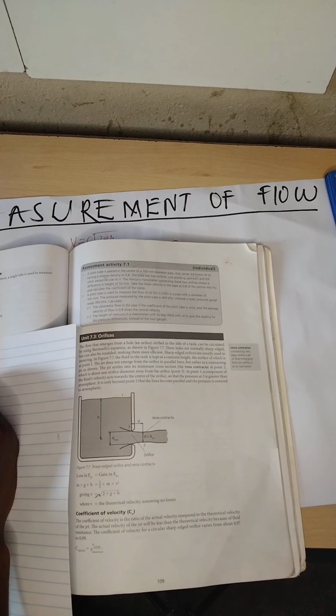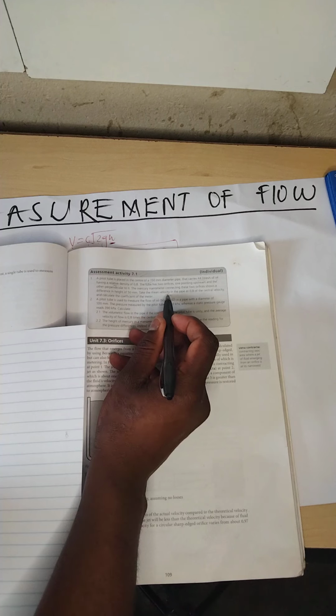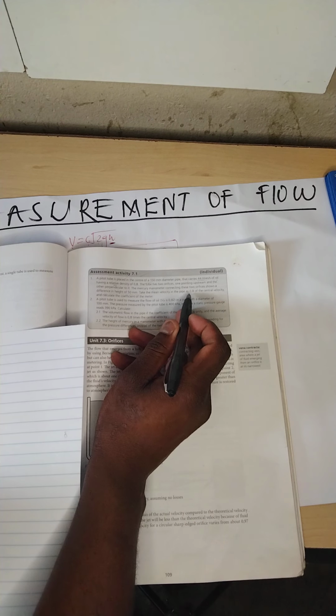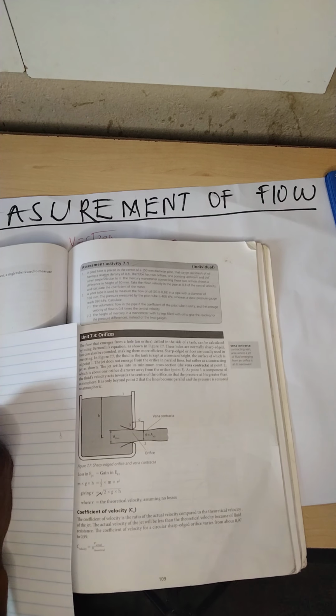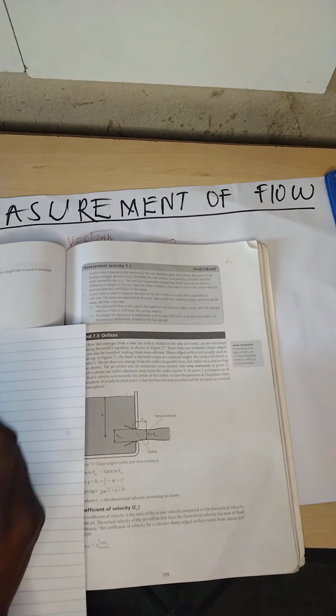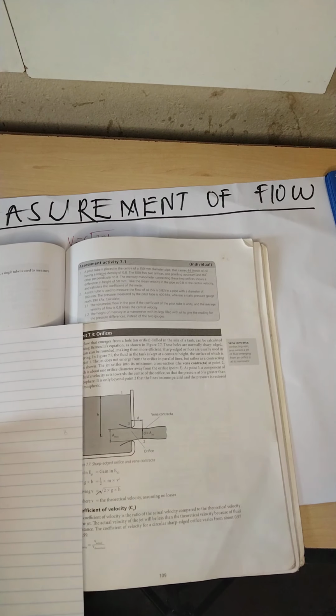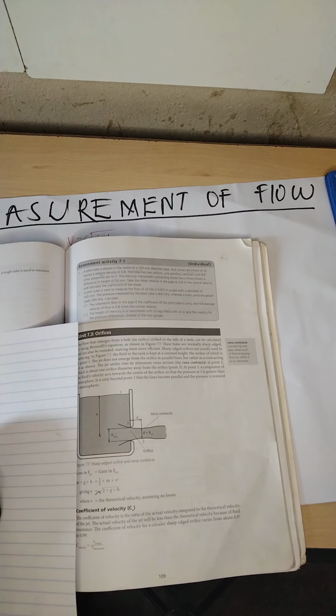It's what? The height of mercury difference is 50 millimeter, right? But take the mean velocity in the pipe. They say the mean velocity in the pipe is 0.8 multiplied by the central velocity. So the velocity in the pipe, they say we must make it as this. It means the velocity that we get after calculating the height, we have to multiply it with 0.8 to get the final velocity, you see.